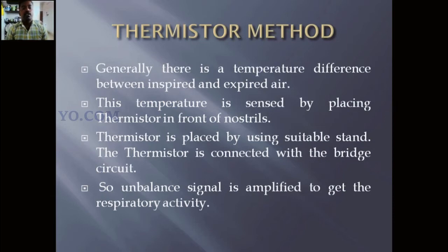The temperature is sensed by placing a thermistor in front of the nostrils. The thermistor is placed by some suitable stand, the thermistor stand. The thermistor is connected with a bridge circuit. The unbalanced signal is amplified to get the respiratory activity. So it's a very simple method.